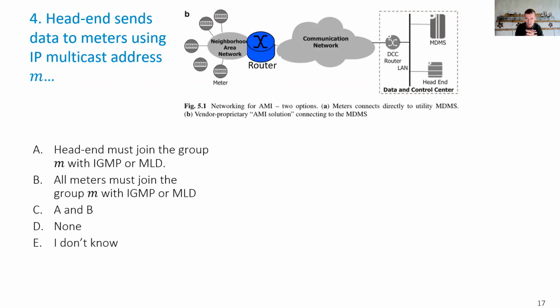Perhaps the most well-known use is when you have TV distribution at home from the operator. You typically receive a power line modem that you can put in a power socket at home, close to your ADSL modem, and then you can distribute the TV signal, which is an IP signal, over power line communication to the room where your TV is. So that's one of the very popular applications. But the other one is to communicate with smart meters. Here I'm assuming the smart meters in a given neighborhood are all connected.